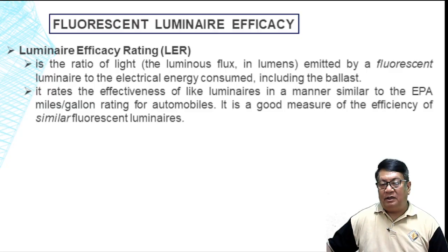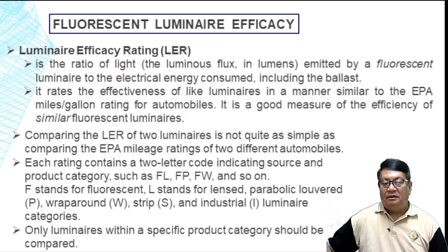Talking about the fluorescent luminaire, the luminaire efficacy rating, or LER, is the ratio of light emitted by the fluorescent luminaire to the electrical energy consumed, including the ballast. Comparing the luminaire efficacy rating of two luminaires is not quite as simple as comparing the mileage rating of two different automobiles.